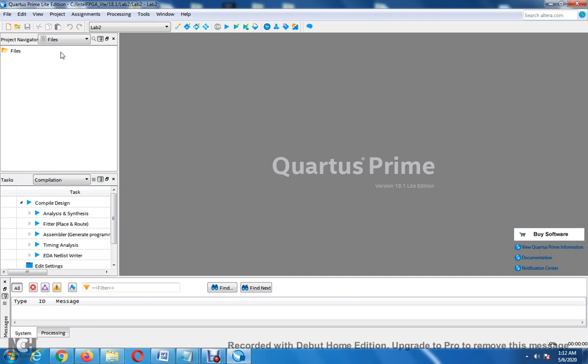At the point where you're going to go to simulation, you have to have two files in here. One is lab2.vhd, which is your design code, and lab2.vht, the same name but in a different subfolder under simulation, ModelSim. Okay, and you don't want lab2.vhd and lab2.bdf. If you get lab2.bdf in here, you have to right click on it and remove it.